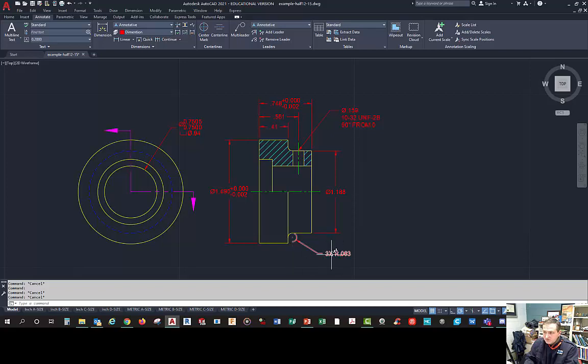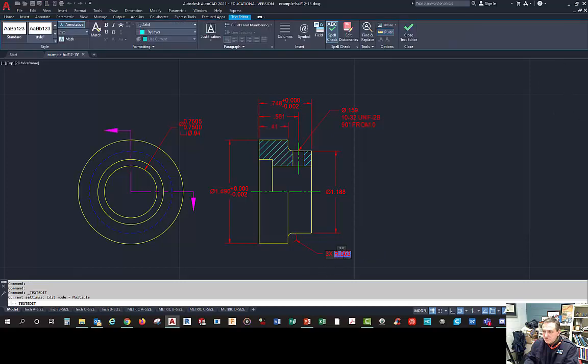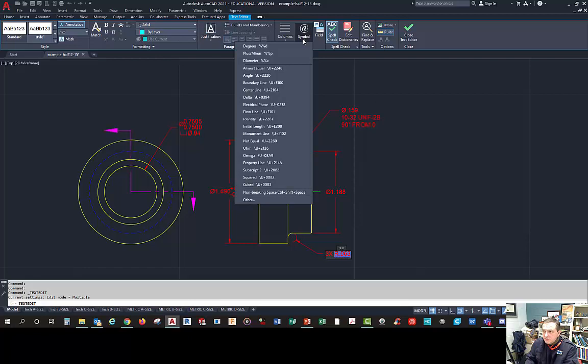Okay, so when you double click on it and you edit it, you've got to remember that AutoCAD put this in, so you don't want to delete it accidentally. So you need to use your arrow keys to go left until you're in front for sure of the text that's defaulted there, the dimension that you want to keep, and then add whatever it is in front of it. I'm in edit mode here. If you need a diameter, if you need degrees, you can add those things in there. Obviously, this is a radius. It doesn't need a diameter.